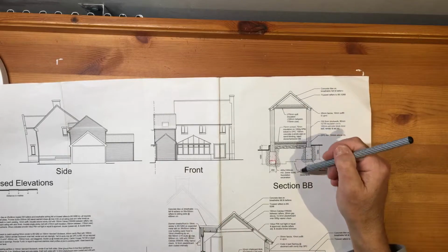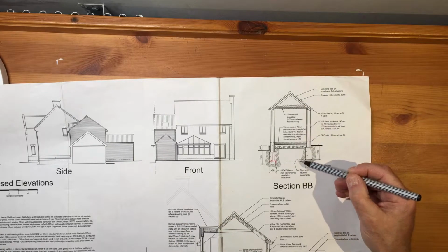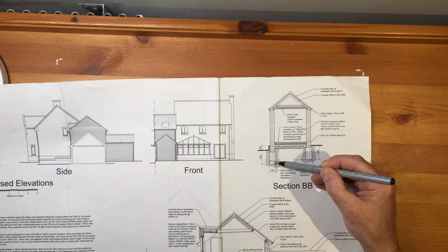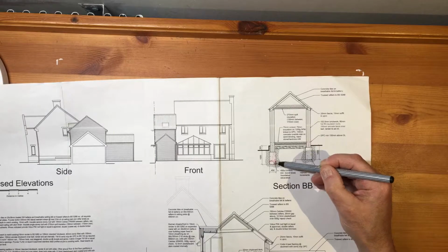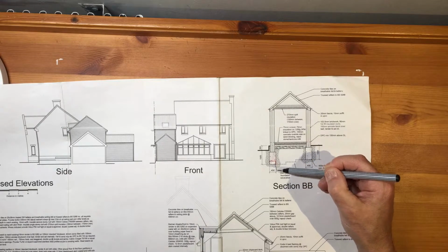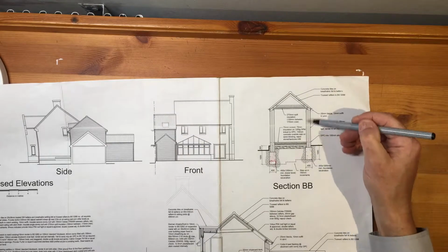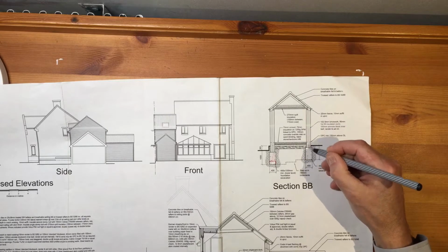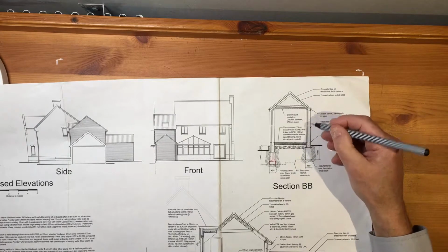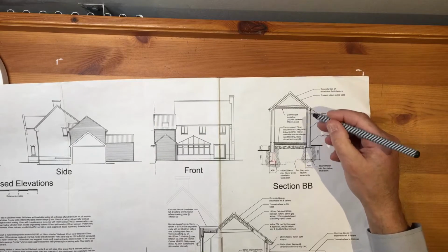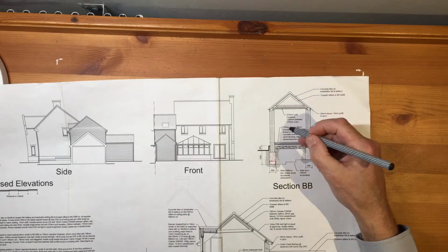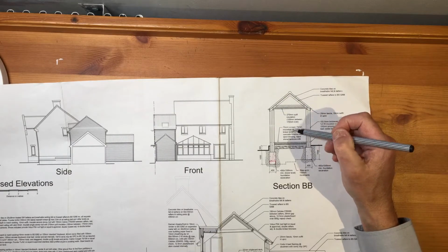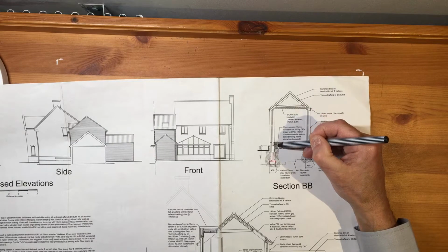Any other questions about this part here? See, the foundations are at different levels. Look, so the ground you can see is at different levels. It's very important the foundations are set at a certain depth, usually a metre plus, to allow the loading of all the structure to be taken into the ground. And that's what the foundation's for, isn't it? To take all the load from the structure, all the dead loads and the live loads, and any imposed loads, the things that you may put inside, or the wind and rain on it and snow that may build up. All those loads, weights, must go down to the ground.